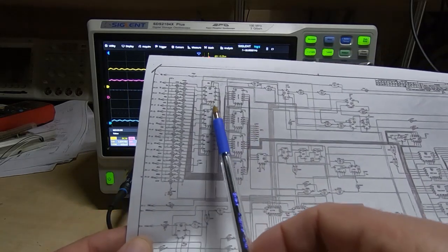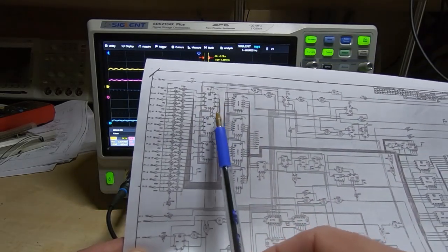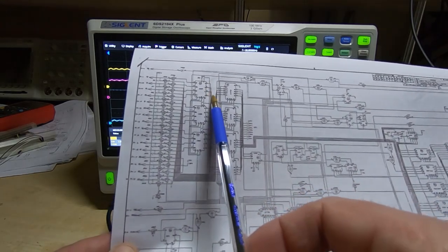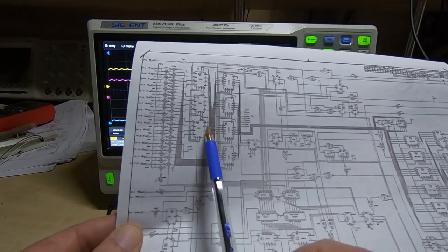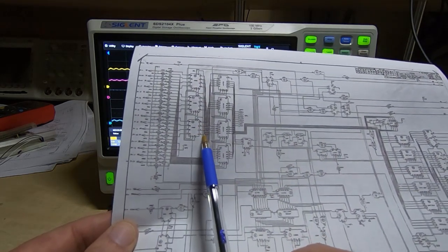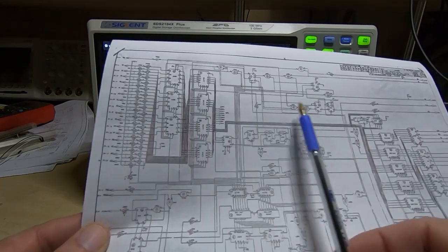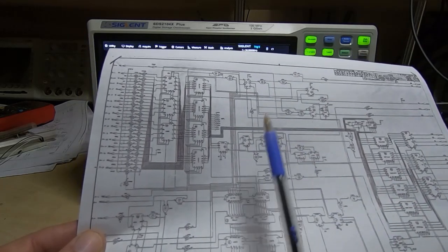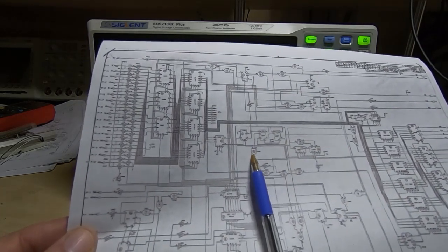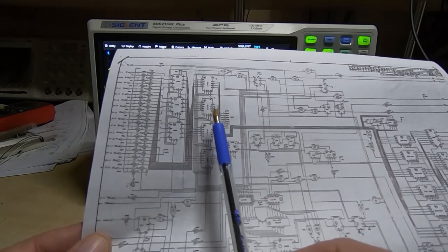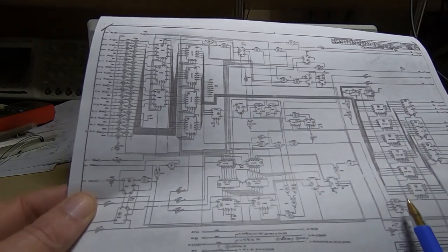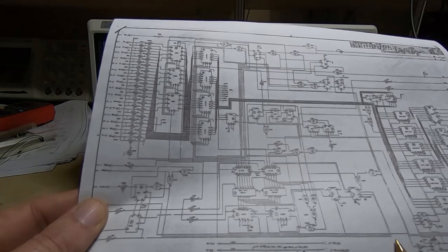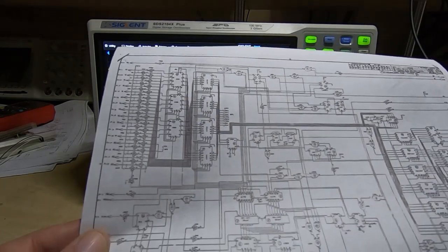So what we'll do now is we'll look at the address counters. I'm pretty sure these are working, but we'll test them anyway, make sure that all the outputs are working. So we should get 12 bits. Not all 12 bits are likely to be toggling. It kind of depends on what the system's trying to display, which is what I'm kind of leading up to. I've got a feeling that this is more to do with what the system is doing in terms of interpreting the incoming data, rather than there being a hard fault in the addressing. But we'll work our way through and try and confirm that. So next thing, we'll check these counters.